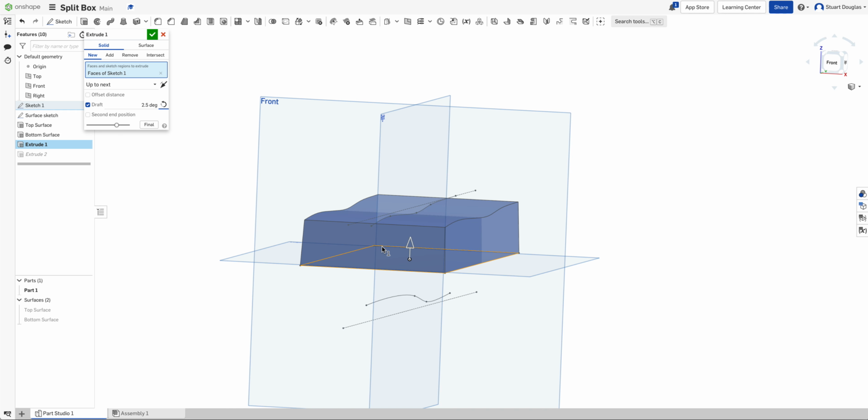injection molded. Okay, it could even be a vacuum formed product. So a plastic product that has been molded. If you are molding any product, then what you have to do is put an ever so slight angle on the product so it comes out of the mold. If it is at 90 degrees, it drags along the side of the mold and it doesn't release. So we have a small angle. Okay, so that's why we do it.